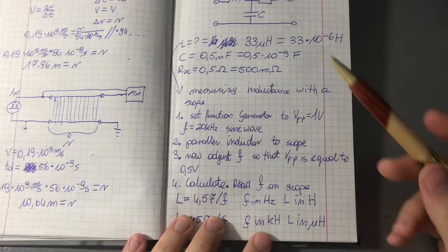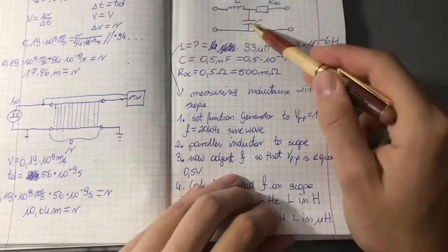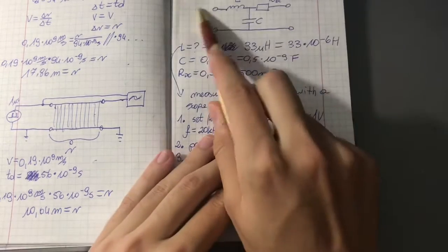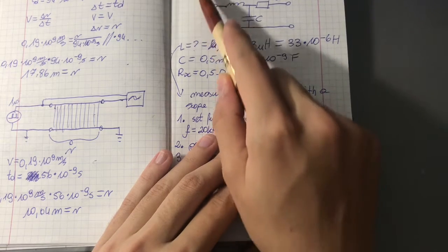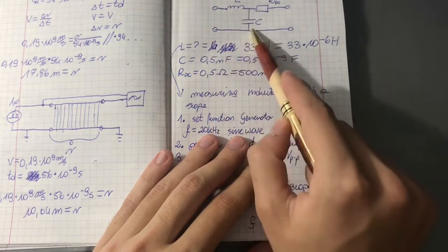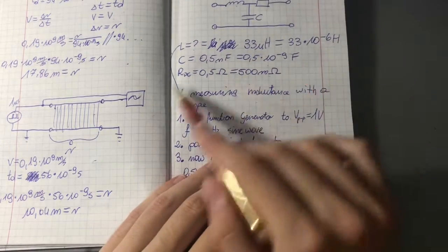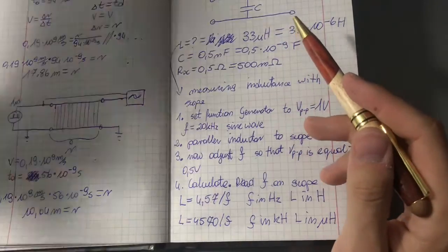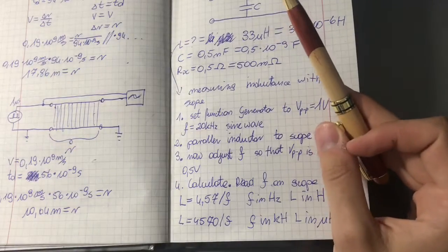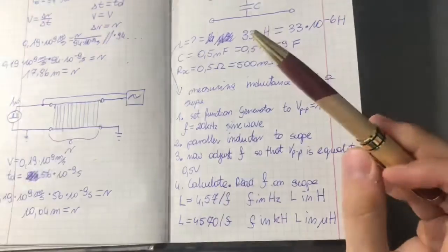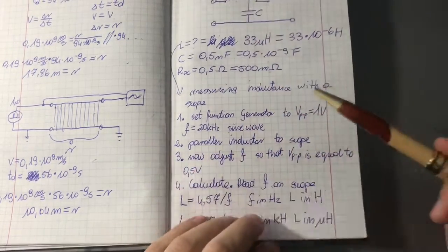Once we have measured the inductance of our wire, the capacitance can be measured with a series resistor here, for example 10 kilo ohm or a bigger one, and then we turn on DC voltage there and we measure what voltage we have on the capacitor. But you can just use, for example, a multimeter. I have one that has a capacitance setting, and I have another multimeter that has a capacitance setting too. So just measure the capacitance with your meter and the inductance with your scope.